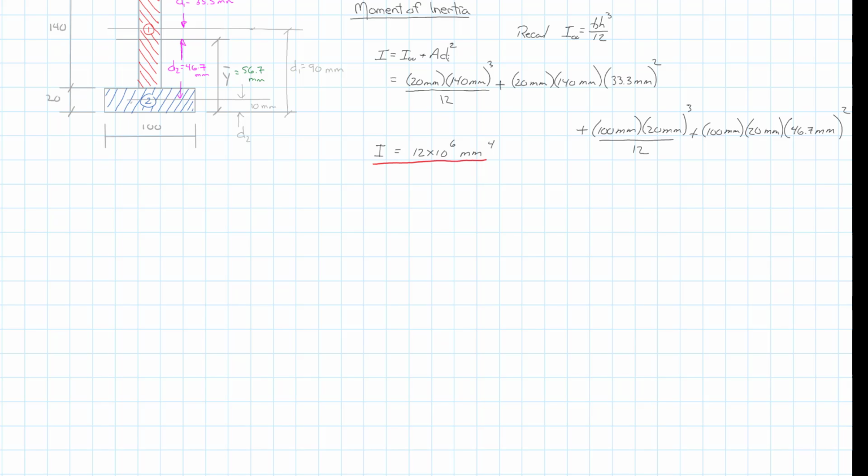So let's just over here, first moment of area. I'll just do one at the web-flange interface, just so that we remind ourselves that this varies over the cross section and we're doing it for a particular point.